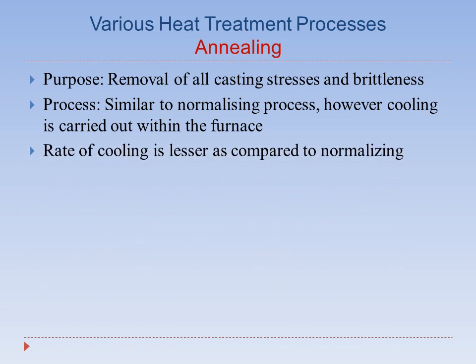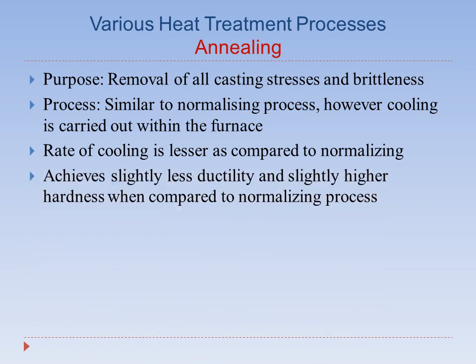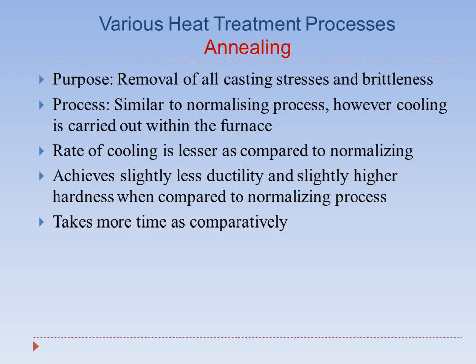So the rate of cooling is lesser as compared to normalizing. It achieves slightly less ductility and slightly higher hardness when compared to the normalizing process. So it takes more time comparatively.